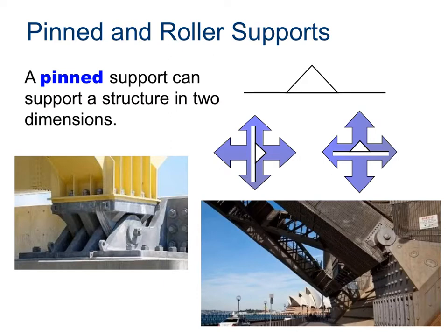You remember we talked about the different types of supports that we'll see on bridges, and one of those is the pin support. And if we remember, this supports the bridge in 2 dimensions. And what that means is that this pin is equivalent to having a force in both the Y and X direction acting on my object. So we want to consider that pin is the same as having kind of 2 forces acting on our object at that reaction or at that support location.